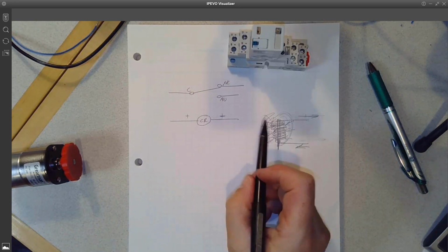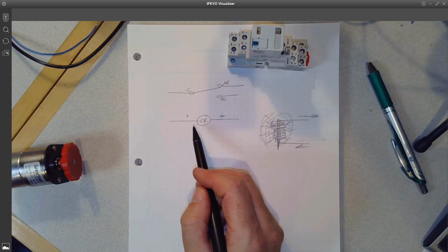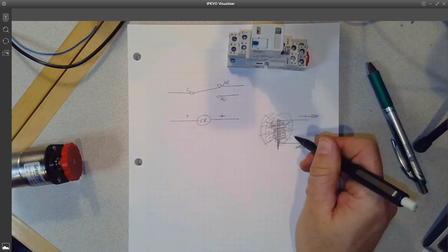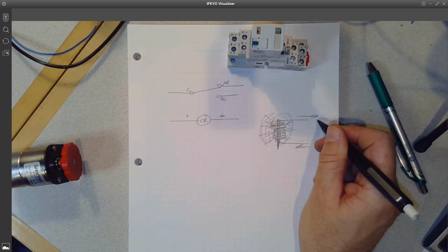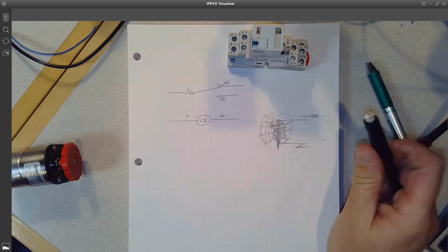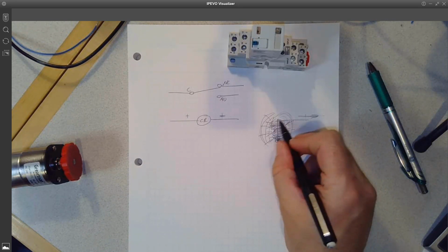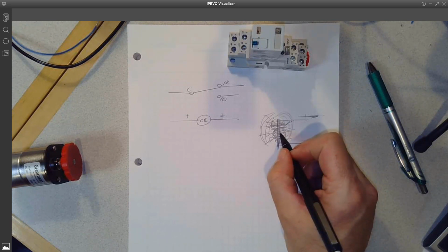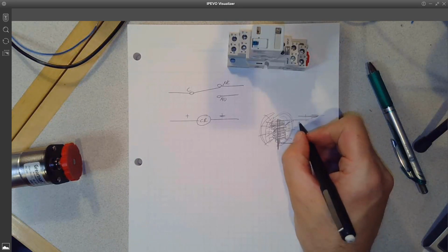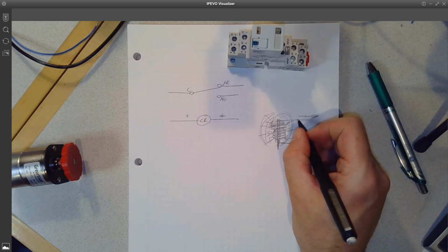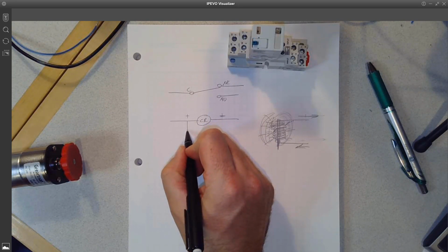And that's important to note because we're going to put a diode around this coil here so that when that flow starts happening like this, instead of that voltage trying to push through our insulation back in the PLC and maybe fry our transistor, we want to just give it a path so that it can just keep dissipating in a circle here, basically. It just wears itself out on the resistance of the coil. So what we would do in that case is put a diode that blocks the way normally.